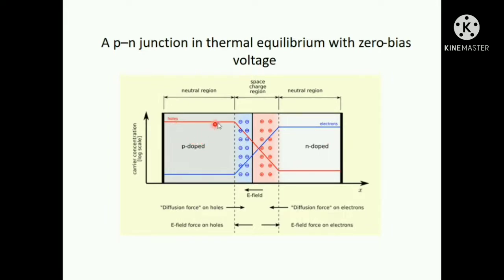When junction is formed, the holes present in P region diffuse into the N region, leaving behind a negative charge in the P region. Similarly, electrons present in the N region diffuse into the P region, leaving behind the positive charge on the N side. As a junction is formed, each region becomes depleted of majority charge carriers around the junction. This region is known as depletion or space charge region, which generates an electric field that acts as a shield between the electron hole diffusion.